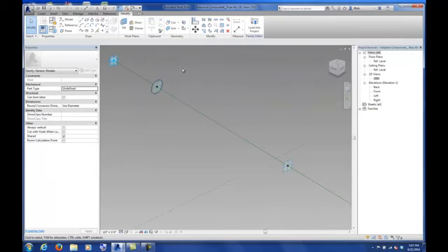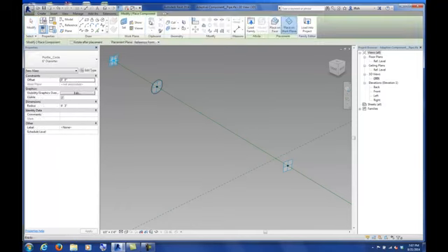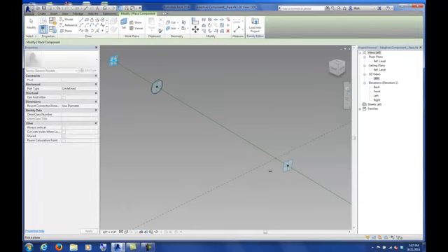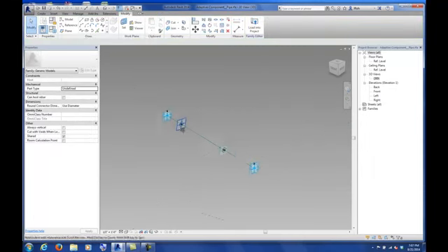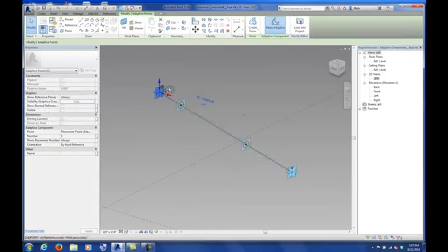So I'm going to do that same set of steps, but I need to repeat it again. I'm going to go back to create component, do placement plane pick, pick the other point, and then again snap to the center there. Now that we've done that, if we move our points around again, you should see that our circles follow wherever those planes exist.